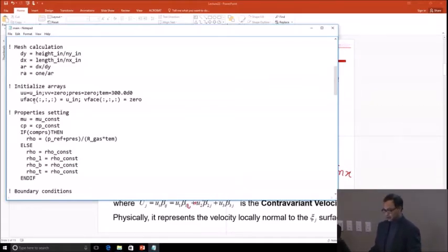See here, initialization. Normally for the driven cavity problem, for example, I think most of you used zero velocity to start with, right? Notice that what I'm doing here is initializing my u velocity as the inlet velocity rather than zero. And there's a reason for doing it. You can do it either way. Obviously, it's an initial guess.